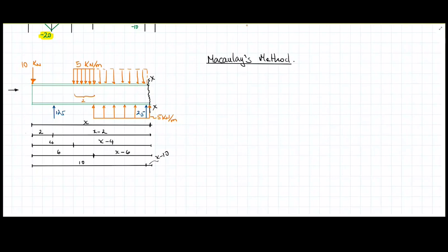When I cut this force, there is a resistive moment appearing here. To call it Mx, because depending on that, when I make the cut, this moment is going to have a value. Next step is to formulate the equation of moments by taking moments of all these forces about the cut, xx. I'm going to consider this as positive, then I'm going to have that Mx.